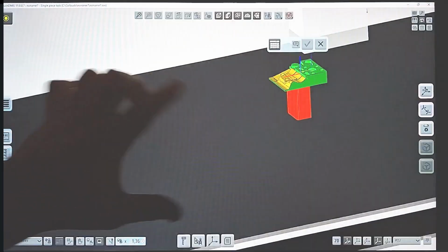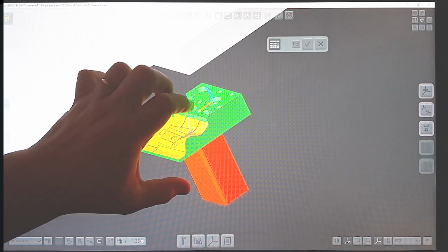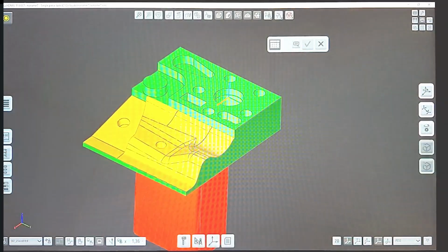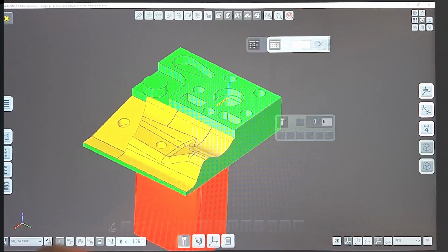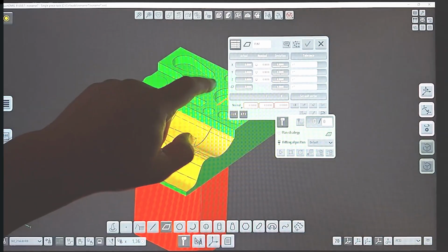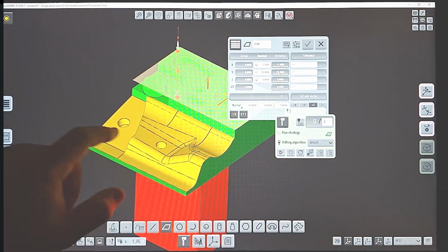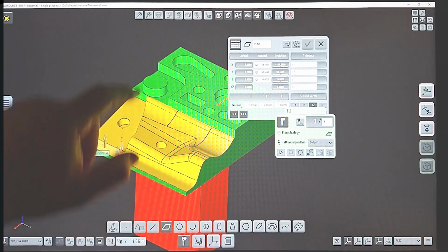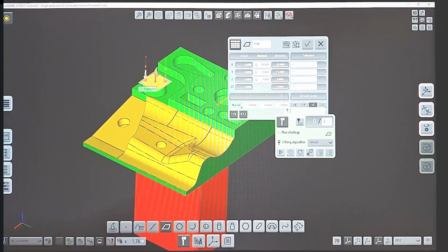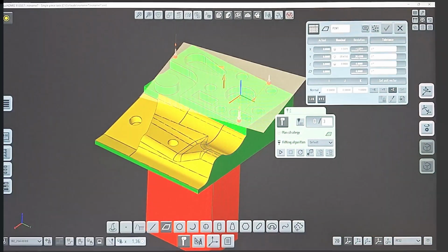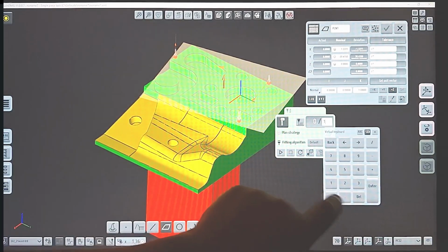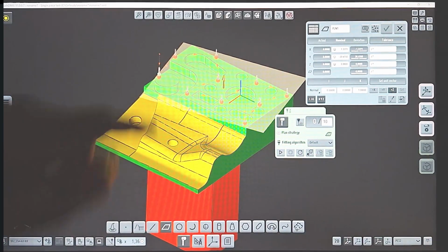Let's explore in TouchDMIS how inspections can be done. For example, let's assume that we want to measure a plane. We go on plane, we select the feature plane, and then we select the geometry. By changing the geometry, we can change the plane we want to measure. The system automatically creates a measuring path, and by changing the number of points, the system will distribute the points along a path that we expect to run.